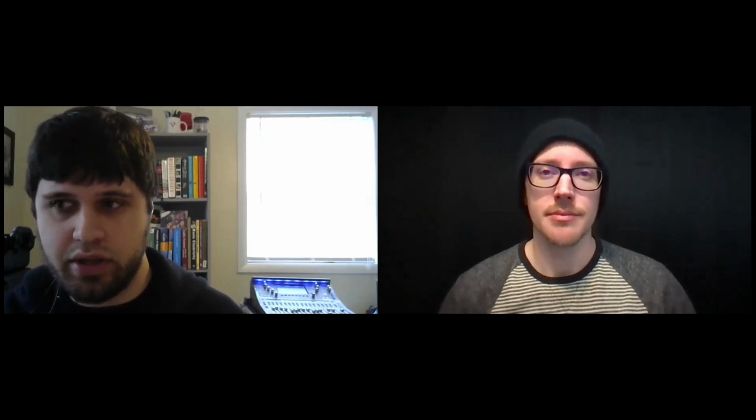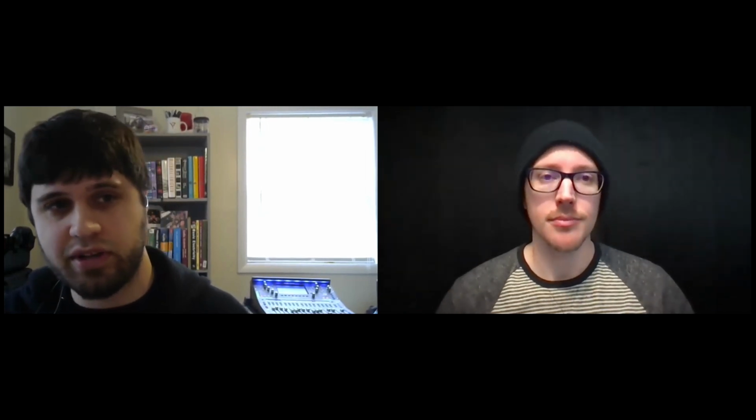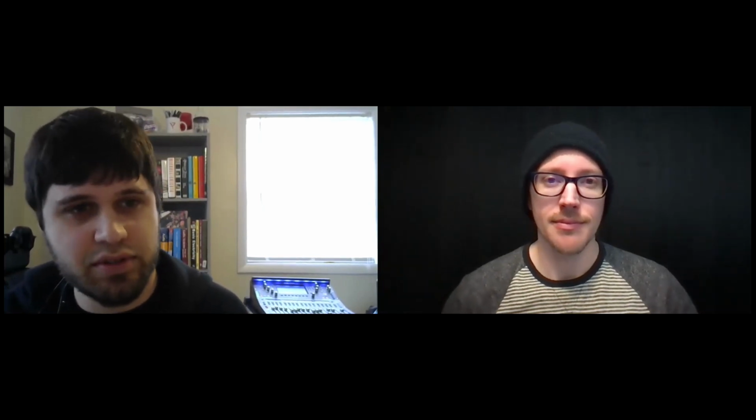So, like you said, it all comes down to what we're trying to do when we pull that analyzer out. This is something that I know you've talked a lot about in your videos: what is the question we're trying to answer here? What are we seeking to learn? If I just want to measure the system real quick and put some filters in, I don't need 70 dB of signal-to-noise ratio, because that stuff lives up at the top, and I'm going to get my answer quickly, and that's great. And if I'm talking to a client about how much acoustic treatment we should order, I want to see what's going on 40, 50, 60 dB down. So that's different tools for different jobs.